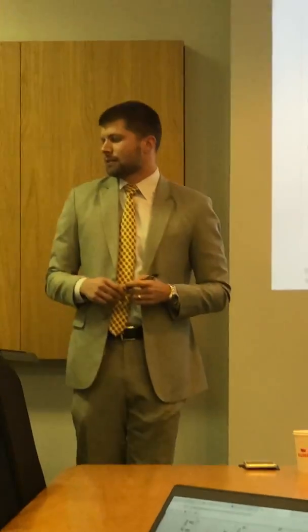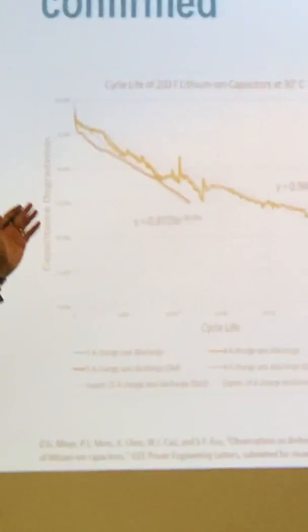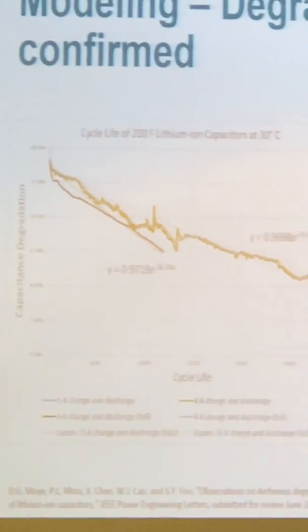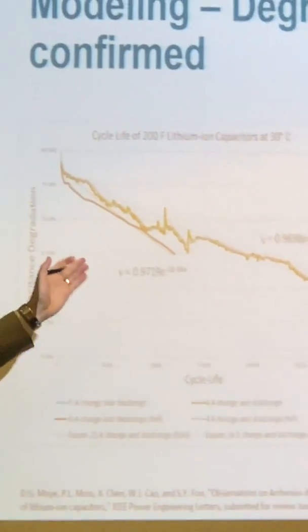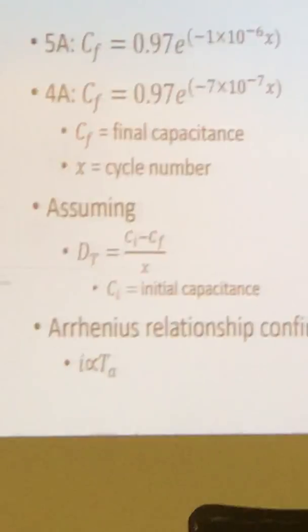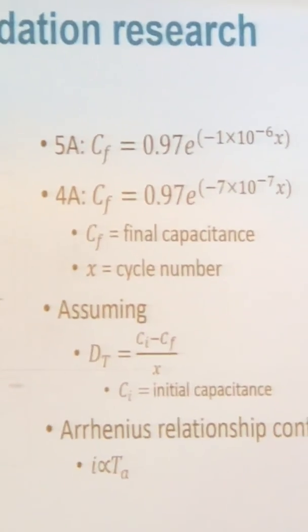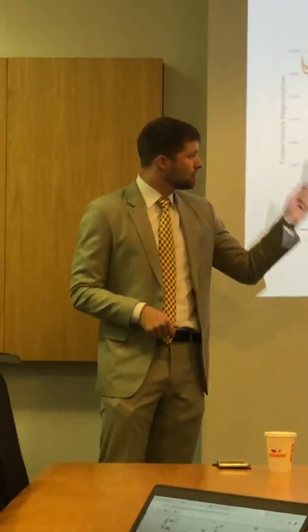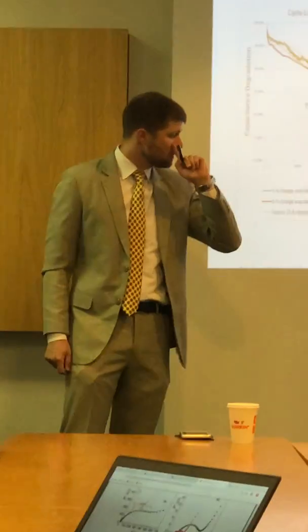So modeling, as I said, I started out with my own cycle life study. So here's the Arrhenius degradation equation that was figured out by Uno and others as a function of temperature. After doing some simple experimental fits of some data I have from General Capacitor, where we're cycling identical cells at different currents, but at the same ambient temperature, what I found is I also get an Arrhenius equation.